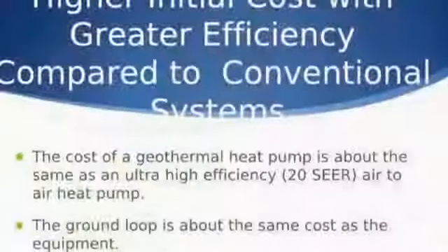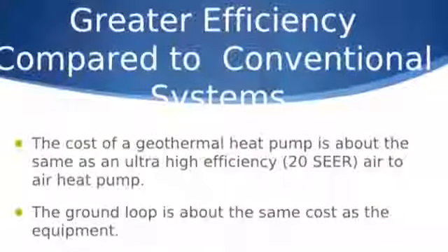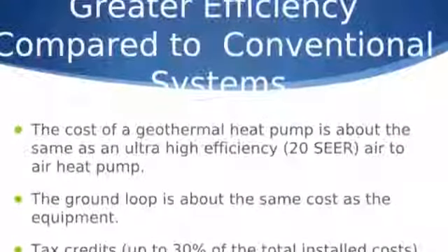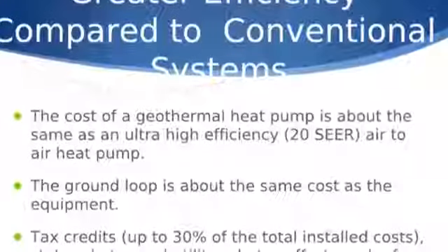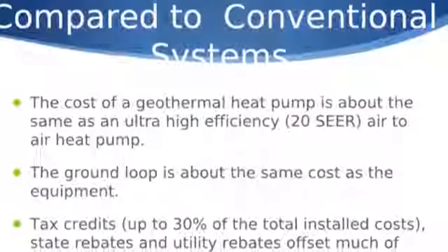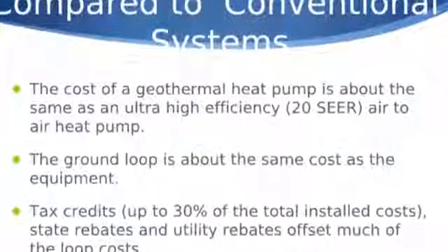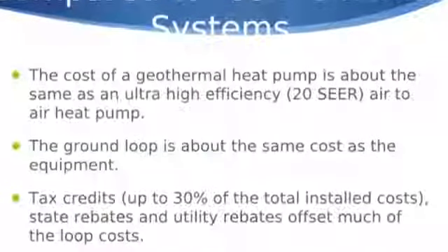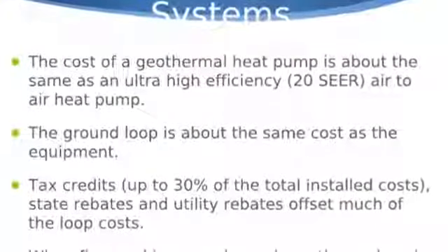A few myths and misconceptions about geothermals, the most commonly asked questions that we get about geothermal systems. First question we always get is, I've heard it's very, very expensive. The geothermal systems themselves can be twice as expensive as a conventional heat pump system. The geothermal portion of it will be no more expensive than buying a 19 or 20 SEER heat pump. The additional cost comes in the loop field.